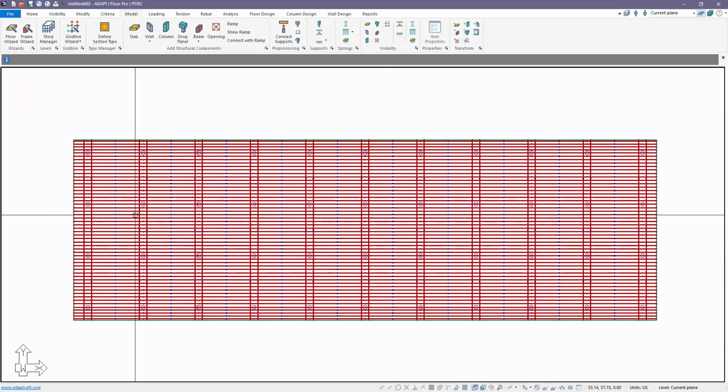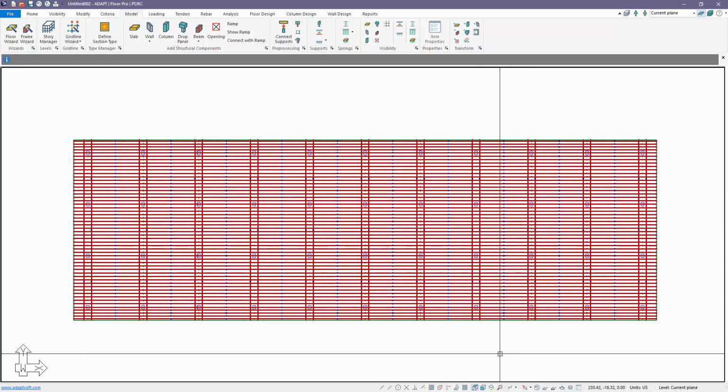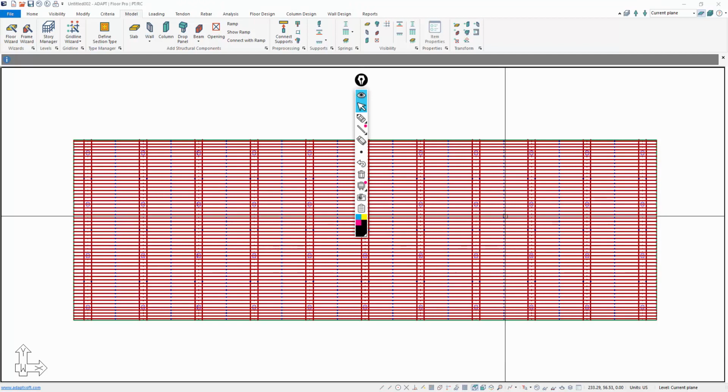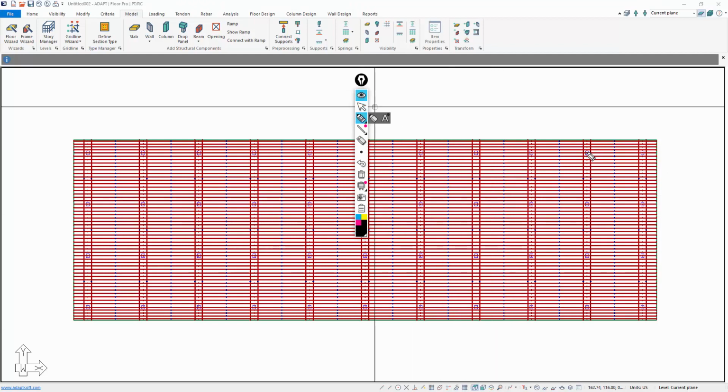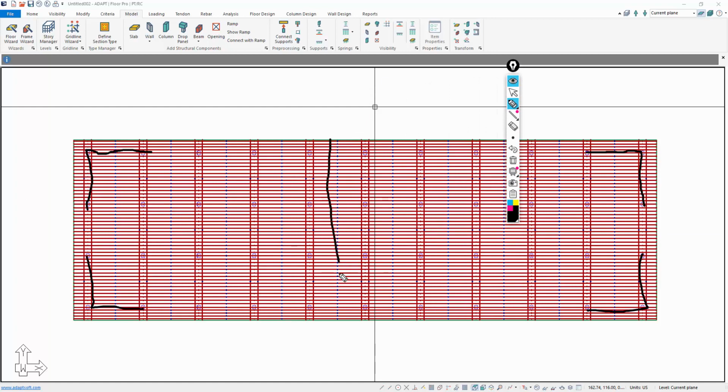Okay, so we have this long rectangular slab, which is really too long, maybe for the length of the tendon, and also if we have any restraint issues in plane, then this could be problematic. We're going to go ahead and actually force a couple of restraint issues. We're going to put an arrangement of shear walls that look something like this, and replace these columns. And then what we're going to do is we're going to say, okay, with this particular condition, we're going to need to add a pour strip.